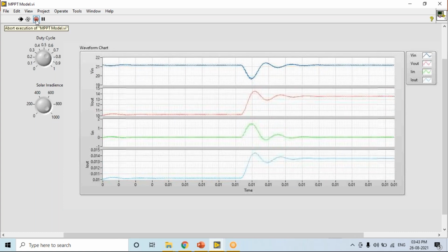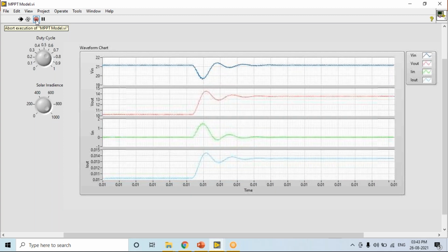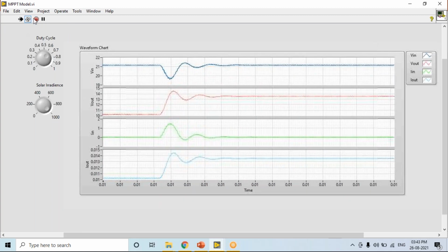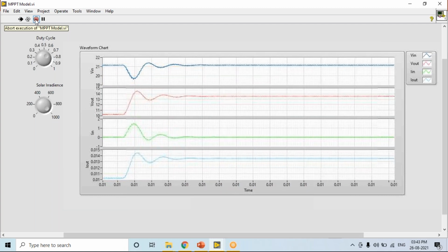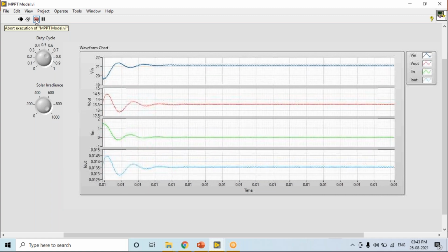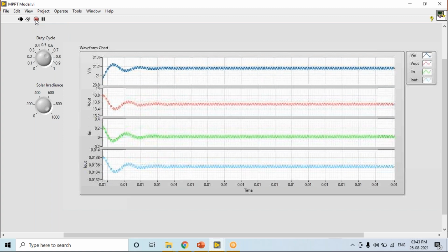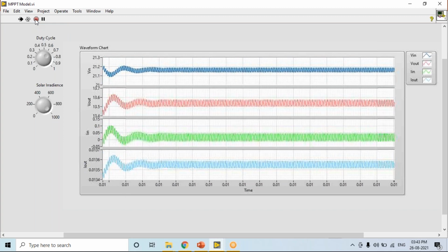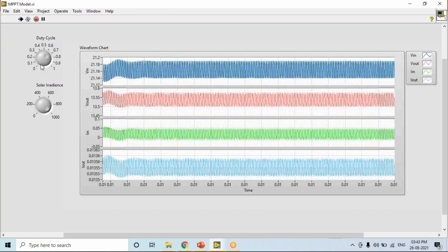By making use of an appropriate closed loop mechanism, you can build an MPPT algorithm by using LabVIEW programming expertise. That you can also do, but that requires a lot of time for us to build it. Or we can use existing open loop or closed loop controllers, like PID algorithms, in order to enforce this closed loop system.